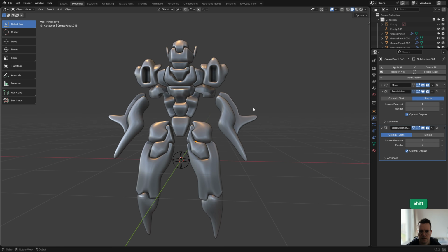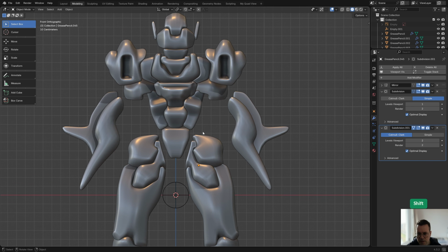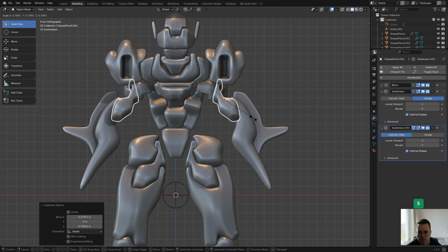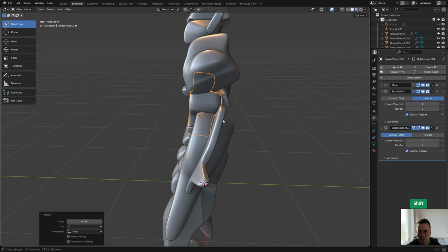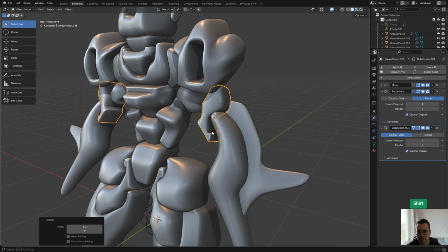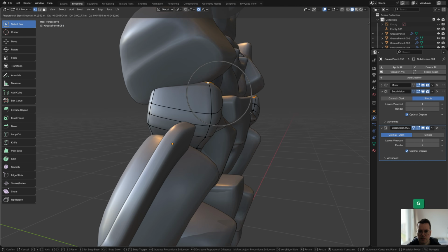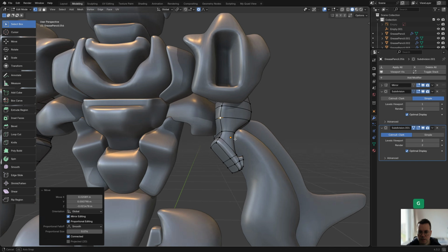And in some cases, like for example here, there's just a big gap between these arms. And that's just because I didn't draw anything in there in the design. And one thing you can do to solve that real quick is just select one of these objects and then just Shift D to duplicate them. And then you can just kind of try to rearrange them, maybe make them fit like this, for example. And let's see from the side, and just press R twice if you want to have free rotation. And then of course we can still adjust this object. So with proportional editing enabled, we can still fine tune the shape. So we can make it fit better in this location.